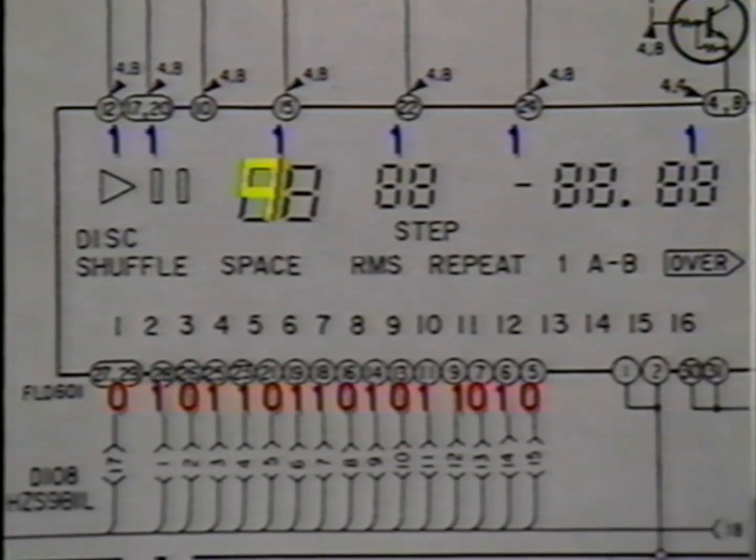So while all digits get the segment pattern, only the correct digit is illuminated by energizing its grid. The microprocessor leaves the character on the first digit for a short time, then turns the digit off. It then outputs the next segment pattern and lights the next digit. Each digit is lit in turn.